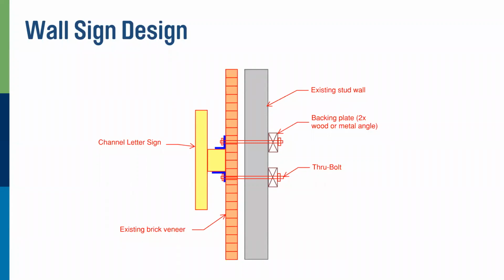If I design this perfect and I put in just a mild steel bolt, well, it's exposed to the weather, it will rust. All right, and another thing that a lot of people overlook is that a lot of times these raceways right here, all this lettering and the box behind it that hides all the electronics, that's aluminum most of the time.